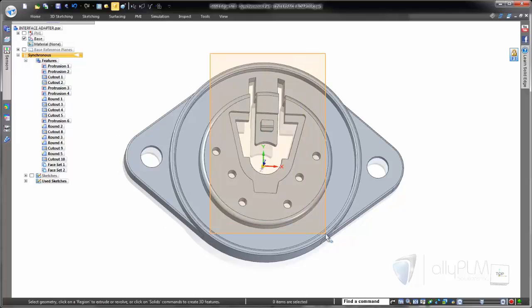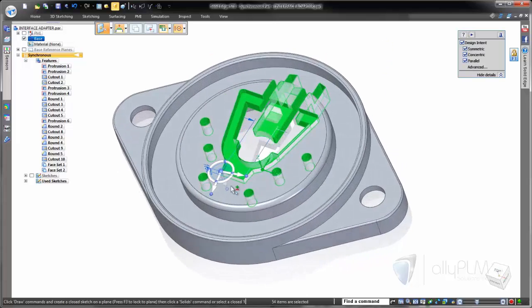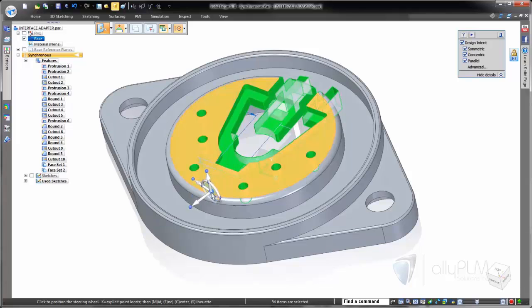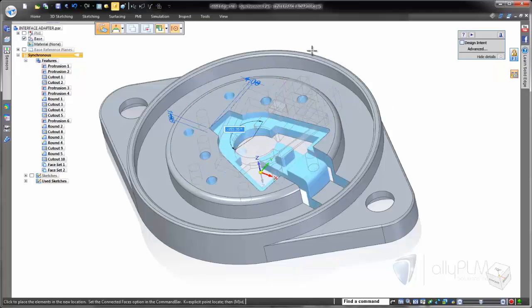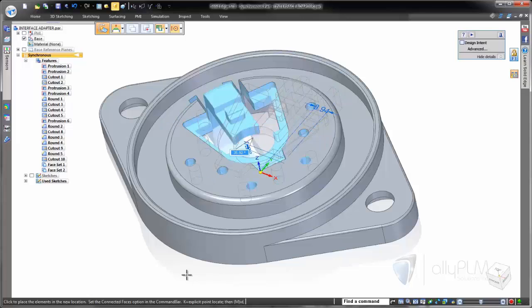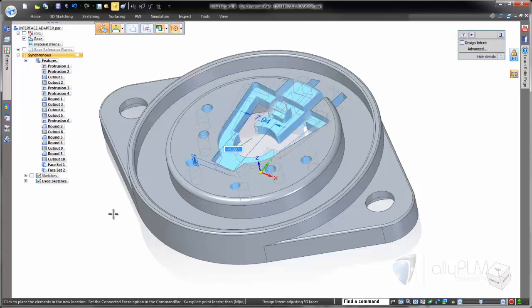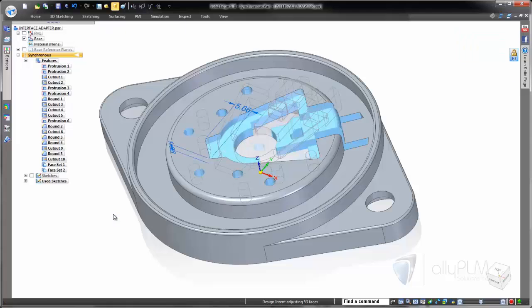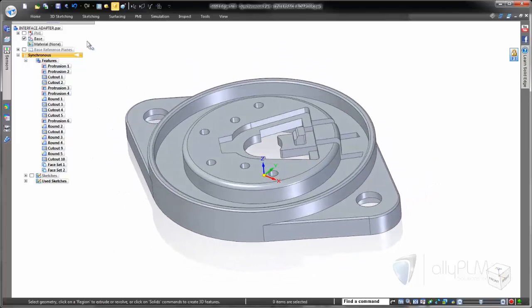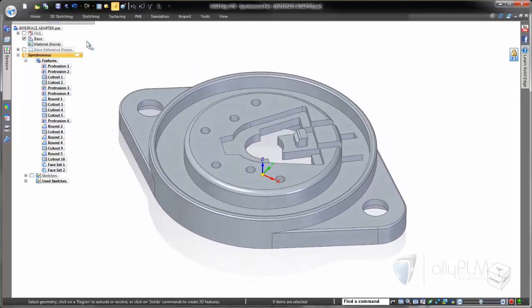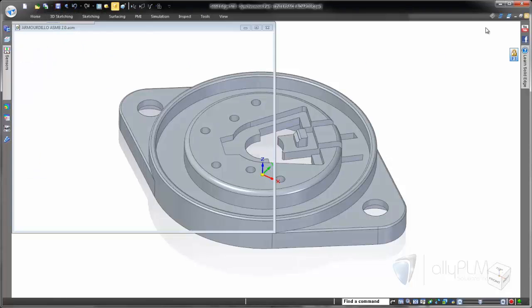For all the geometry that we wish to modify in the select set, we can simply disable all design intent relationships by unchecking the design intent entry or by pressing the U shortcut key. This ensures that only the geometry that we selected will get modified. Again, this new design intent panel is intended to replace Live Rules as it was in the past. The feeling with development is that this is a much simpler way to understand how this functionality works.